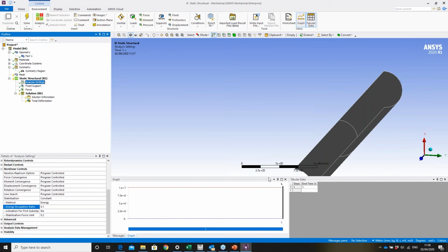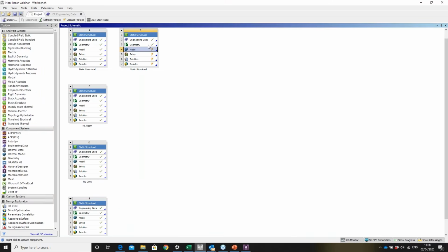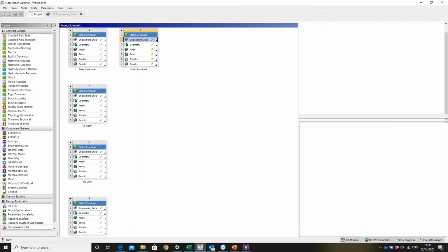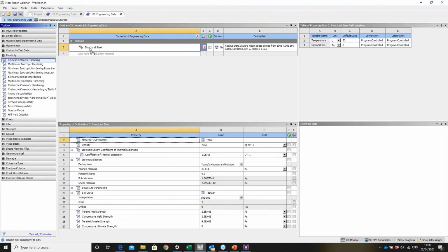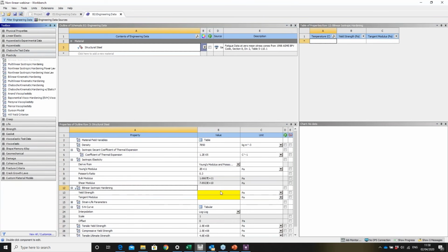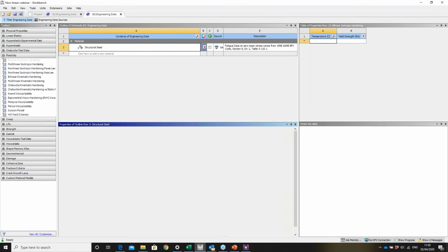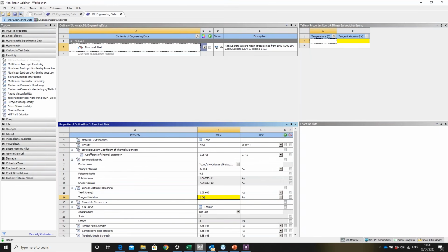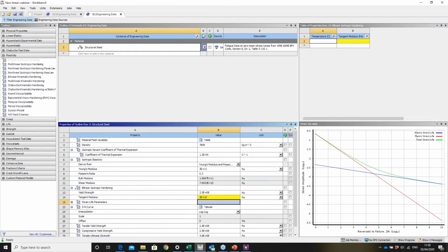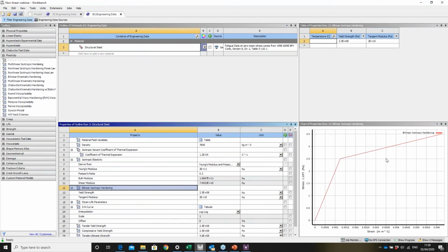However, there is one step that I missed out here. For this type of analysis, large deflection needs to be on, and also you usually need nonlinear materials. So I'll just go in and edit my default steel. I'll use the values we saw before, so we'll convert this to a nonlinear material from a linear material.